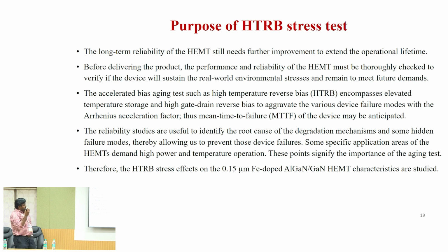So even though these HEMTs are potential candidates for RF and power applications, their long time reliability has to be studied. Okay, so how much duration can that device work for a longer period of time, that you have to identify. But you cannot wait for a longer period of time, because your device performance will degrade with elapsing time. So you cannot wait that much time for the device to fail after 2 years or 3 years, like that.